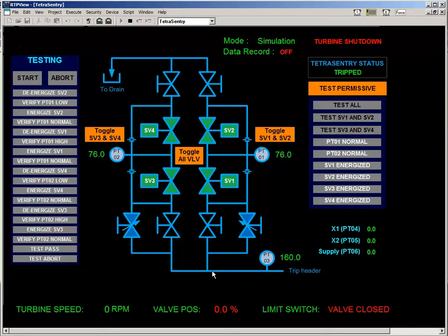That's because as the oil passes up into the block, it goes through a pair of serially connected orifices that pass through the inner valve cavity. So these 2 orifices are the same size, which will result in a pressure between the orifices of approximately half of the overall pressure across both of the orifices.